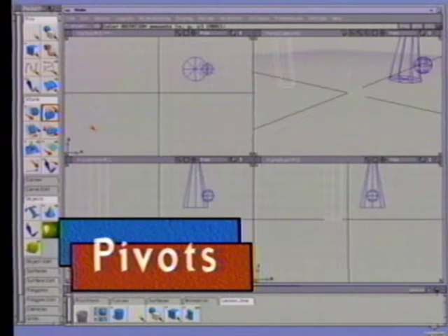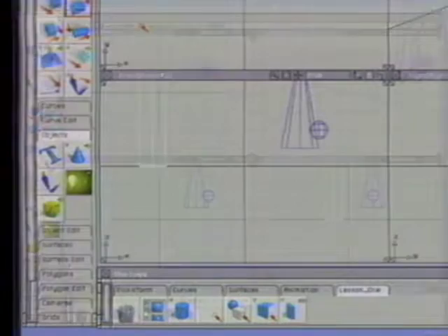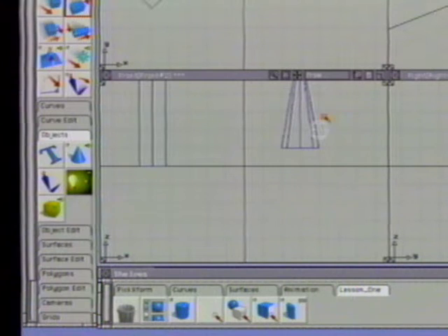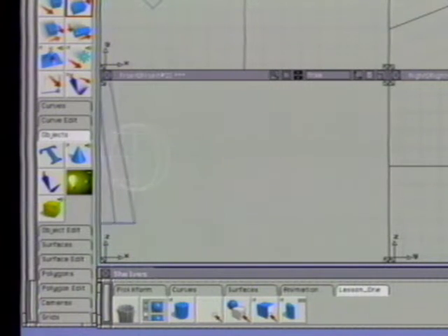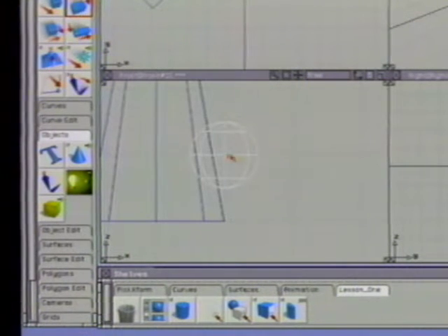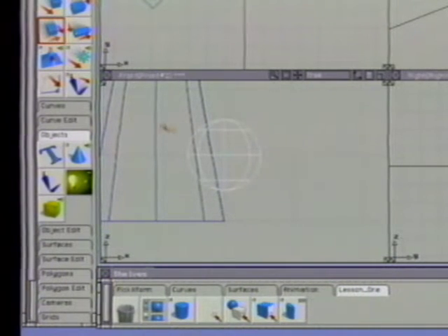When you transform objects, they are transformed based on pivot points. These points represent the anchors of the objects for translating, rotating, and scaling the objects. Click on the sphere to pick it while unpicking the cube. In the front window, dolly in to see more of the sphere. You will find the pivot point at the sphere's center. From the Xform section of the tool palette, select the Scale tool. Click Drag to scale it. The scale will be based on this point.